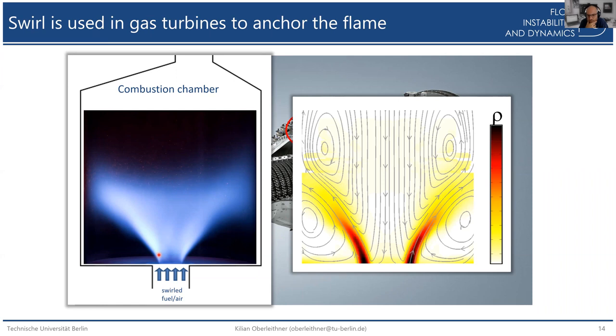If you look at some PIV measurements in such a combustion chamber, they look like this. What you see is a very strong recirculation or reverse flow region in the center of your flow, and an annular swirling flow going around this recirculation zone. And then, of course, you have some very strong shear layers. This inner shear layer is where our flame is stabilizing. So we are using vortex breakdown to have an aerodynamic flame stabilization. However, as I told you, there are a couple of hydrodynamic instabilities that become important for this type of flow, and this may affect the combustion process.